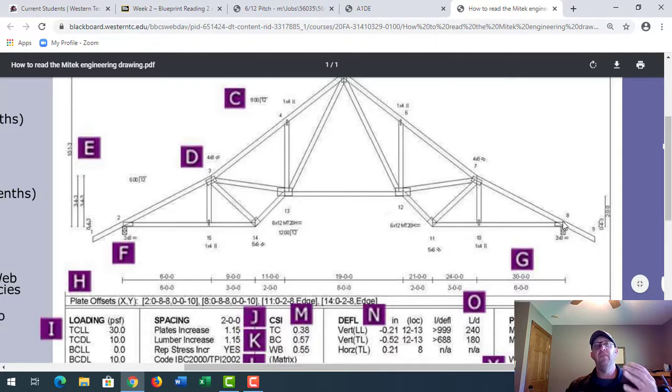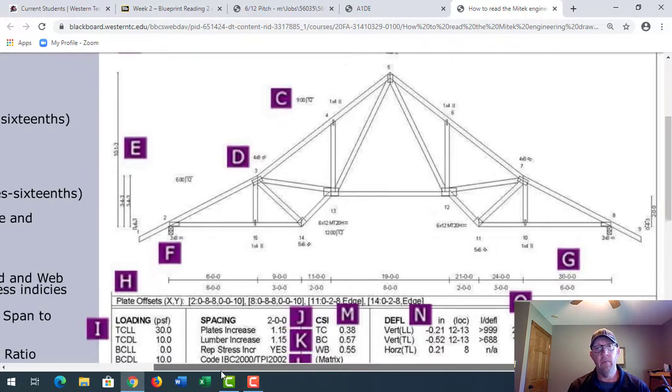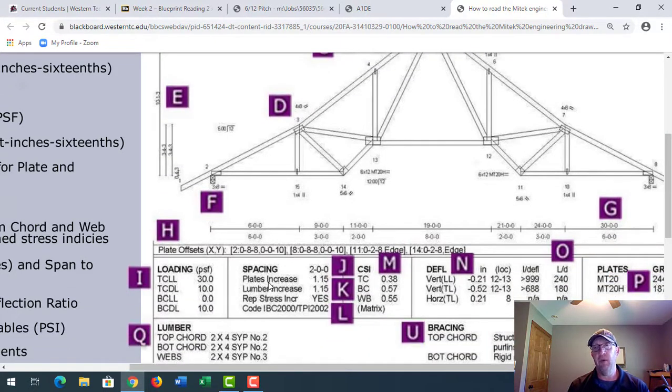Trusses are designed for live loads and dead loads, and then they're designed to distribute the weight equally so that the weight is sitting on each of the walls. So why is this important? Well, if you had a structural truss, something like a girder truss, for example, we would want to really know how much weight is sitting on this outside wall, because it might require us to add studs underneath inside the wall cavity to transfer our load down to the foundation. So in this example, this is how you would figure out a truss reaction.